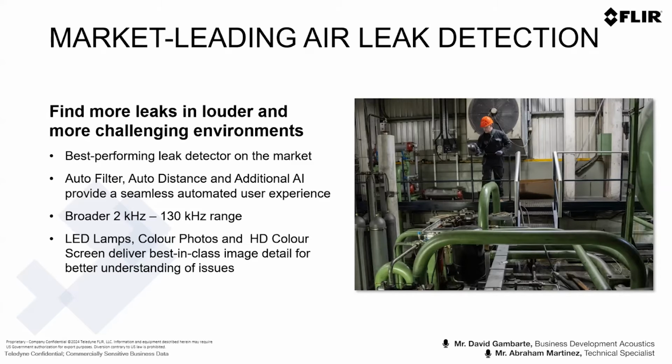We recommend to do it sharply. If you want to get a good calculation of the leak size, please use any kind of measurement tool. Of course, the easy one might be a laser, or your own eyes, like 5, 6, 7, 10 meters is fine. You need to use your own kind of tools for the distance. But yes, we recommend to do a sharp distance detection or distance selection, because it might actually affect the leak size. Of course, it depends on the use. If you just want to fix all the leaks that you find, it doesn't really matter. Whatever the leak size is, you will need to fix those leaks.